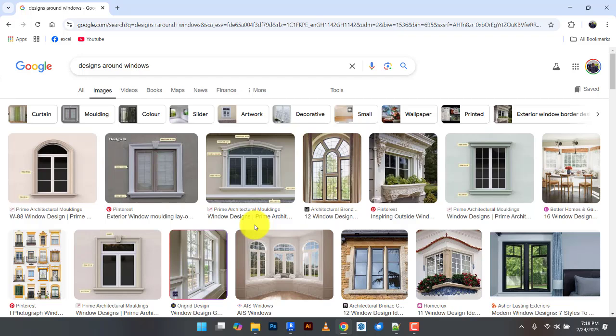I wouldn't say it's impossible, but it's stressful and not worth the time. Because it's model in place, if you do it at one side, you can't go and use it at another side. You get it? Okay, I mean, you can technically. What you may have to do is select the window, go to the edit family of the window where they created the window, then add it as part of the window, then save it. Then when you load it back into your project, it will come with it.